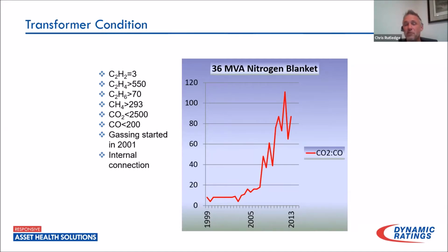I also had several transformers where I saw these large drops in ratio, and these would be wet transformers and that type of thing, where this ratio would drop and I wouldn't have a lot of gassing present to indicate that I was having a problem. So that's why it is important, even if you are going with key gas type monitoring, that you keep up those annual samples and do those trends, because again, with certain types of failure situations, you're not going to see any of these hot metal gases being produced. However, when you would see that drop in that ratio of 70% or so, generally you would be within 2 to 3 years of failure of that unit. That would also be reflected in offline testing usually.